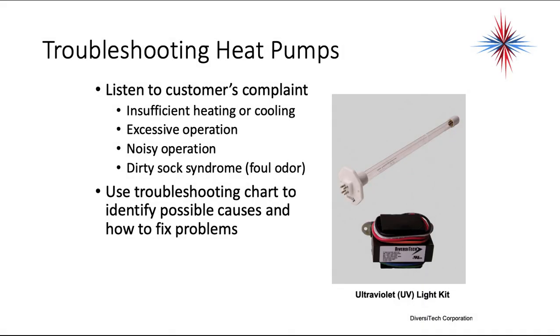Troubleshooting heat pump systems, make sure you listen to the customer's complaint. Insufficient heating or cooling, excessive operation, noisy operation. We have a thing with heat pumps called dirty sock syndrome. It's a foul odor. Use a troubleshooting chart to identify possible causes and how to fix problems. Most heat pump manufacturers now put out troubleshooting charts.